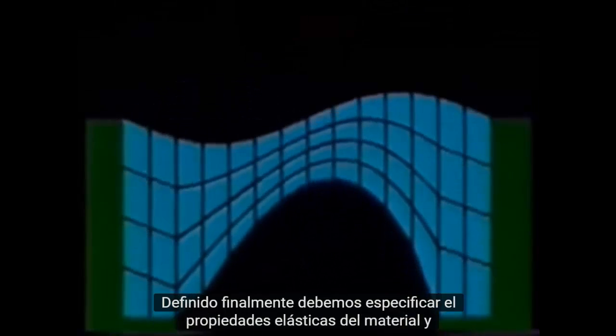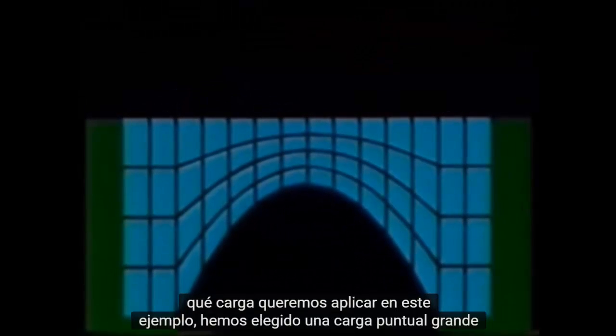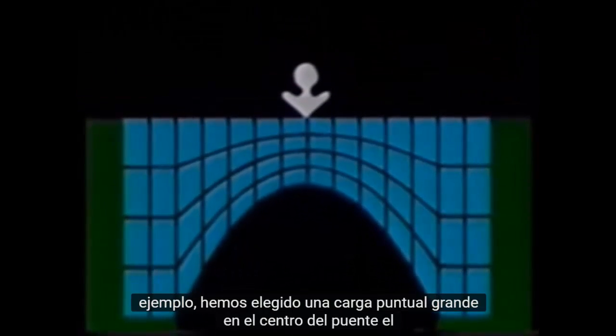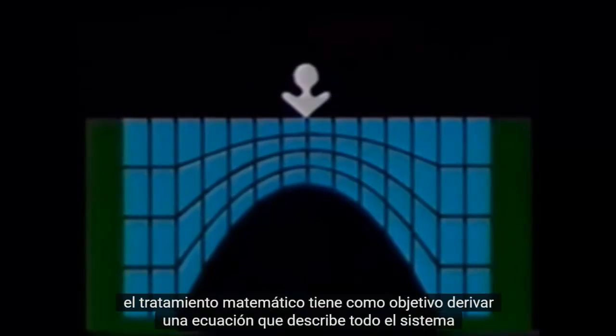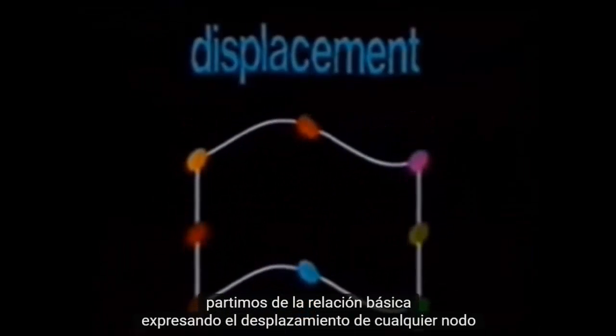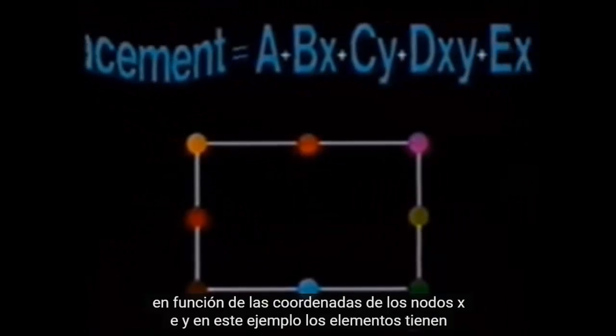Finally, we must specify the elastic properties of the material and what loading we wish to apply. In this example, we've chosen a large point load at the center of the bridge. The mathematical treatment aims at deriving an equation describing the whole system. We start from a basic relationship expressing the displacement of any node as a function of the node's coordinates x and y. In this example, the elements have 8 nodes, and for each of these, we write an equation describing the displacement of the node as a function of its coordinates. This gives us 8 equations for the whole element, which together form a matrix.